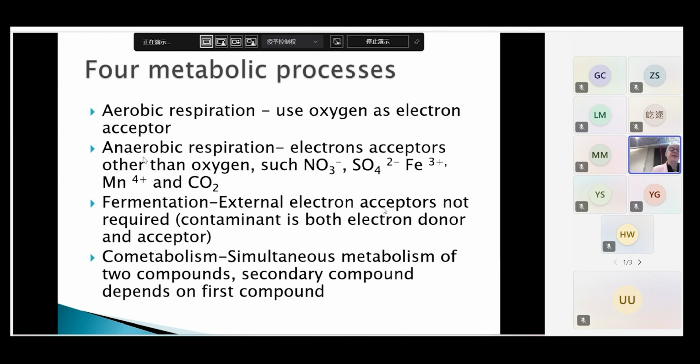You could also do thermal type systems where you're heating the soil, or soil washing. These are some other options. This was the same type of biopile system that I had mentioned before. I brought my students to this site this past summer. They treat contaminated soils and so on, and it works quite well, very low cost.